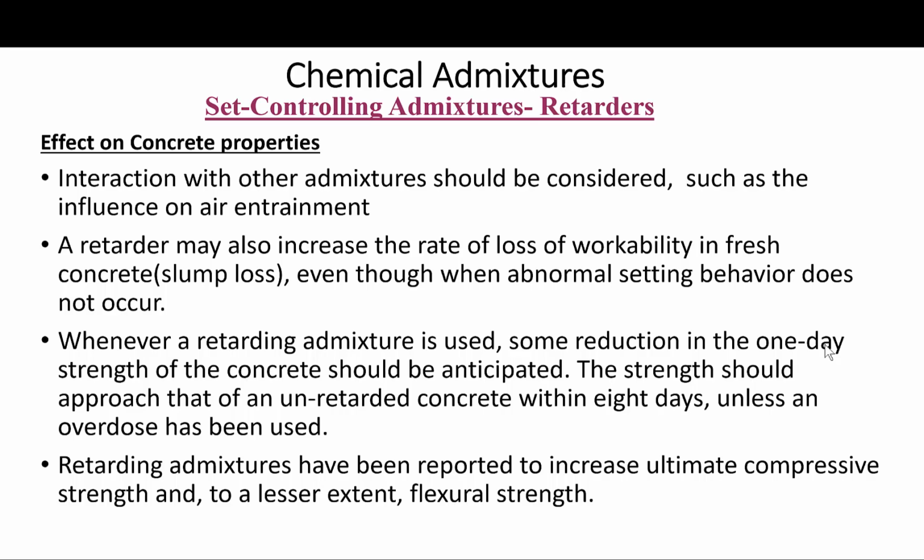So consequently, an additional dose of water-reducing admixture can be used during retempering of a fresh concrete, basically without prolonging setting times unduly, and without compromising the performance of the hardened concrete, which adding water will do, okay?